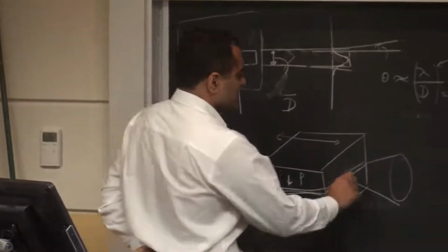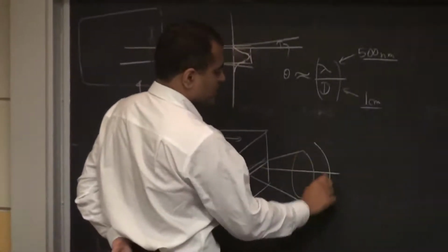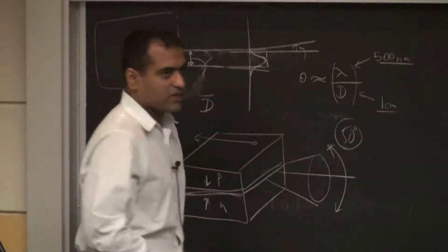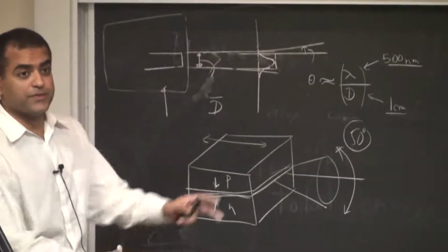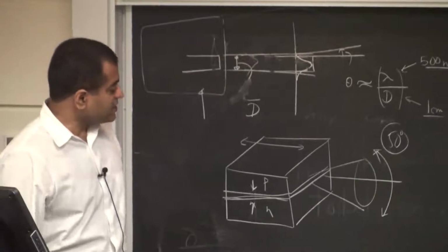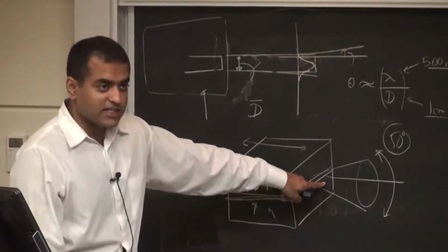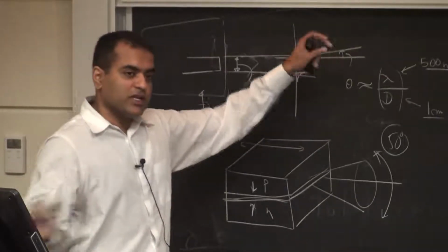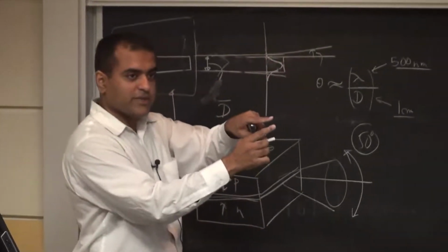And in a semiconductor laser, the angle is actually terrible. The angle at which it comes out is about 50 degrees or so. It comes out as a large cone. But it's a laser, it's not an LED. If it's a laser, no matter how much it is diverging, you can pull it all back again and make it a collimated beam. That's the beauty of the laser.